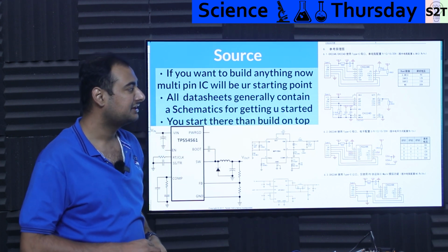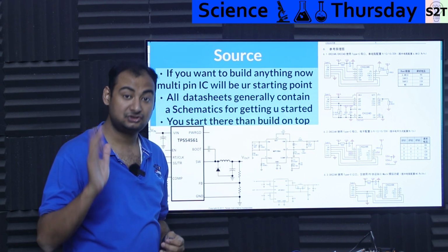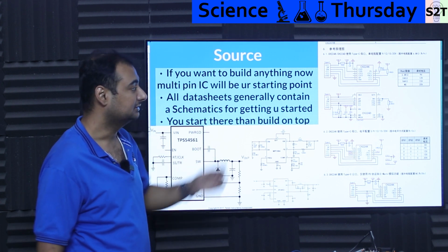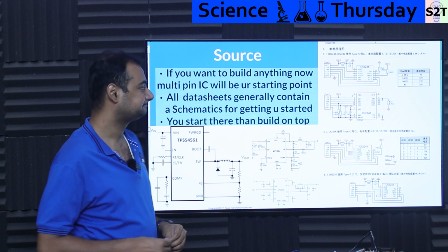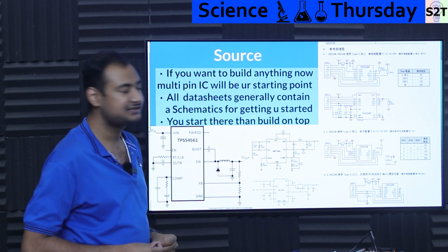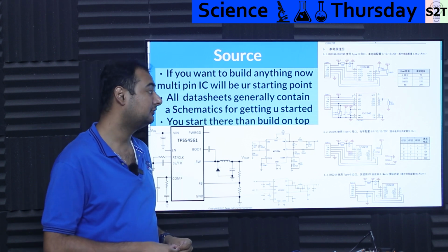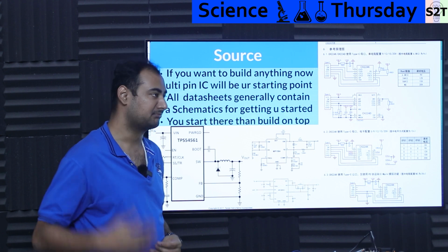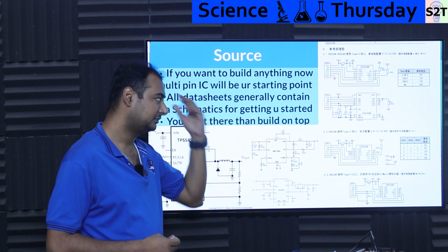Where it's like, hey, you connect a 6.8 kilo ohm resistor, we're going to assume that you want 9 volt output, we're going to handshake 9 volt. You put a 24 kilo ohm, we're going to assume you want 12 volt, we're going to do a handshake with that. You put 56 kilo ohms, we're going to assume you want 15 volt. You put nothing, not connected, we're going to assume you want 20 volt. You want maximum power delivery standards. Okay, go, you learn it.